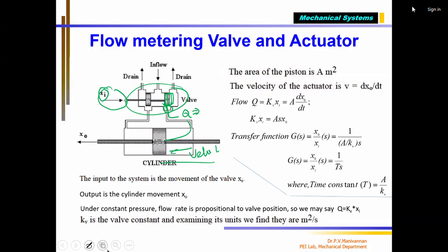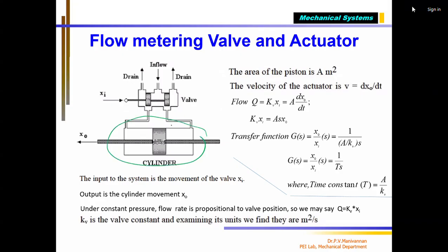Okay. So now, we know a mechatronics system means you have a mechanical system, and it should be powered by an actuator. I have the actuator. The actuator should be controlled using a control system. So this is a control valve. They call it a control valve. So now we have to write the model equation for the power cylinder with control valve.